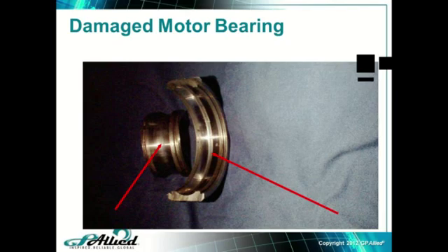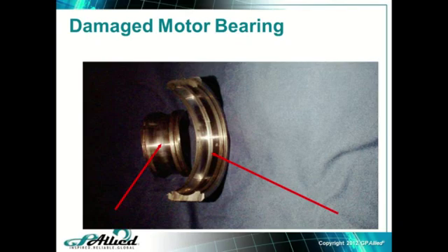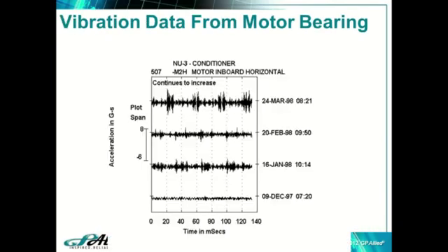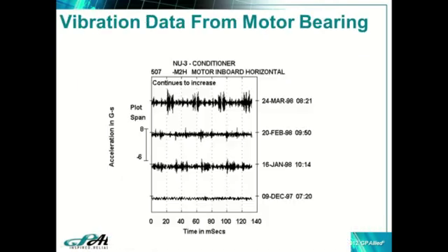What happens next? We leave those long enough. Oh, by the way, if you want to see the vibration data for that, it looks like this. December 9th of 1997, there was no problem. January, the subsurface fatigue began. February wasn't much different. March, the subsurface fatigue moved to advanced, and you could actually see the time waveform. You can see it starting to happen. So took the bearing out, got some cool pictures of it.